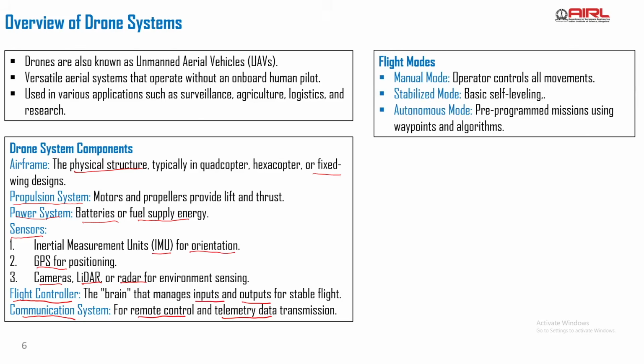Manual mode is usually not for beginners. It's for advanced operators who can move the drones to perform certain maneuvers under loss of some information, right? Probably due to loss of GPS, I can take it into manual mode and operate and bring it back, right? Stabilized mode is for beginners, right? The aircraft has an inherent ability to stabilize and maintain a certain orientation, such that the remote operator can easily drive the drones to whatever action they want to perform.